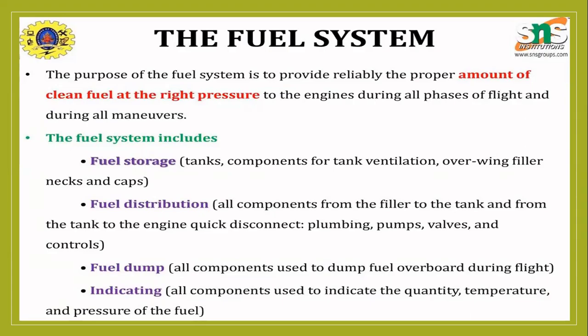That is why when the fuel goes down, air will automatically come inside and replace the vacuum. So there is no shape change in the fuel tank. That is why tank ventilation is needed.